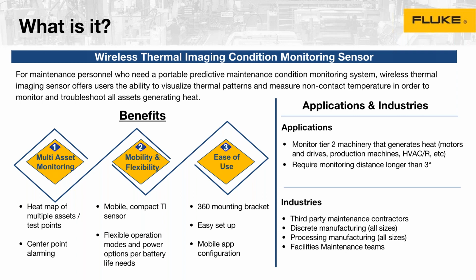Obviously, there's the mobility and the flexibility to use this. I'm going to use this for a week on this piece of equipment. I'll get enough data to do a baselining, and then I'm going to move to this other piece of equipment because I need to monitor it over the long term. So for the next 2 months, I'm going to leave the sensor right there, and I'll see if there's truly a trend of increasing temperature on the bearings on the front, as an example.